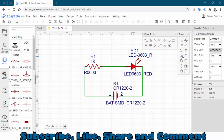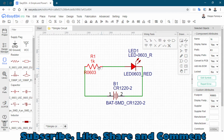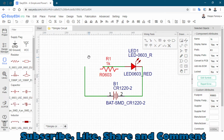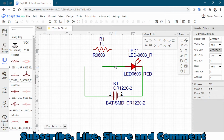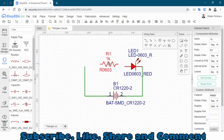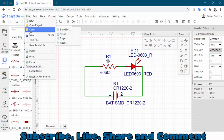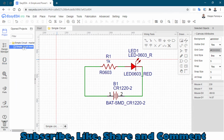Now click on this hand and move this resistor a little bit here by using the arrow key. You can place the resistor right here, and now connect this resistor with wire like this, and from here to here. Now our circuit diagram is complete. Now we have to press Ctrl S to save it, or you can go to file and press save. It will be saved. Okay, now here we have the sheet 1.